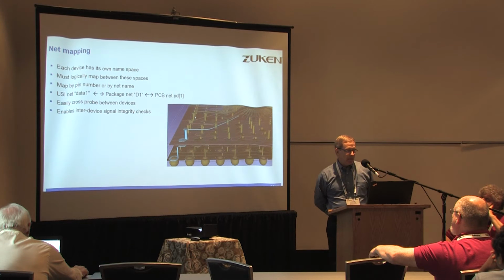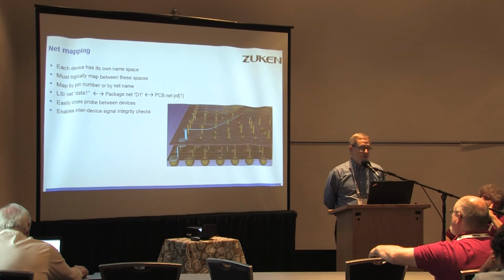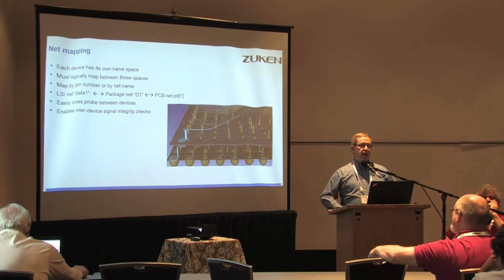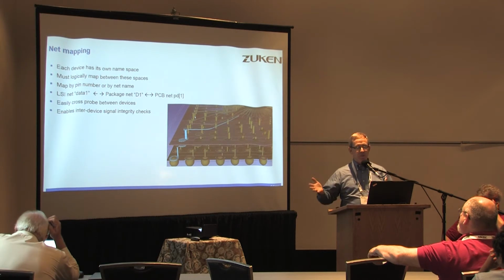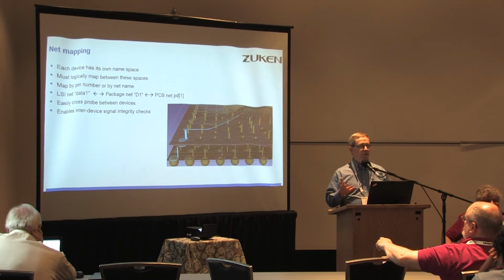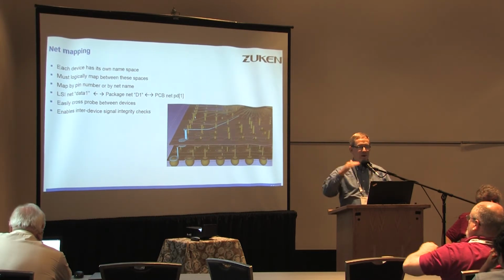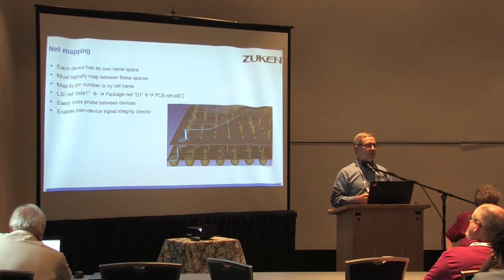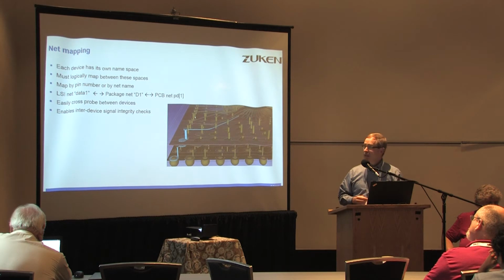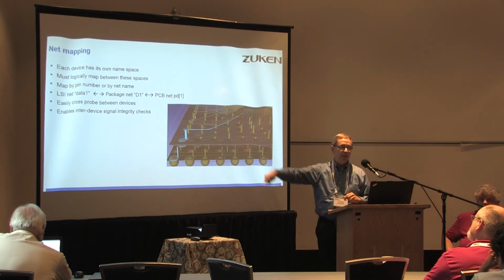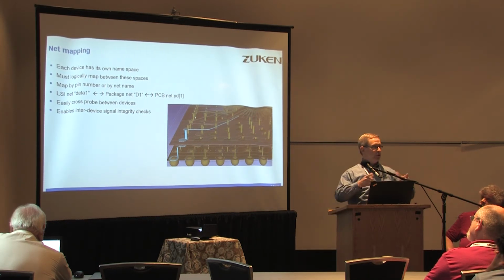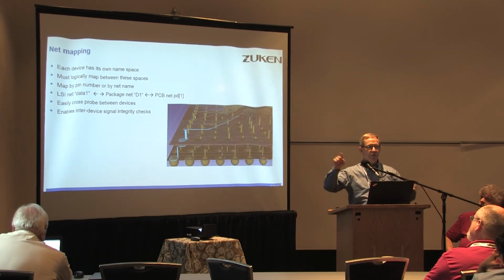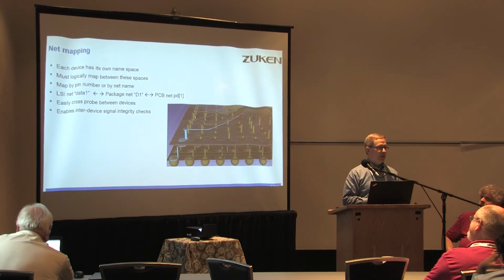Net mapping, I mentioned before, is critical to do properly, because if you've got a 5-die stack on a package on a board, or a fan-out wafer level type of design with multiple dies and a PoP on top, you're going to have different names for the same signal depending on what space you're going into. Design Force gives you the ability to map between those. You go into 3D, click on a net, regardless of what context you're in, and it'll follow that net throughout the stack, and you can see where that's going and what's happening to it.